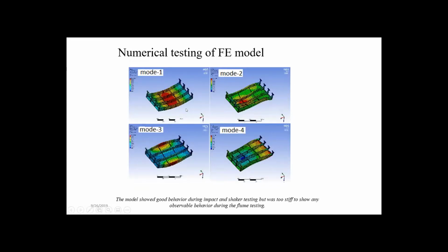Now, this is very important because if you have a truck crossing a bridge, it has a certain weight and crossing with a certain velocity, and if that truck can generate a frequency that matches the frequency of mode 1, say, for example, 5 hertz, then the bridge will deform like this. If the truck can generate a frequency that can excite that mode, then it's going to be this. And from here, you can see very clearly, this truck can cause a lot of stress in this connection between the girders and these cross beams. And so forth, this one, it can affect the abutment.